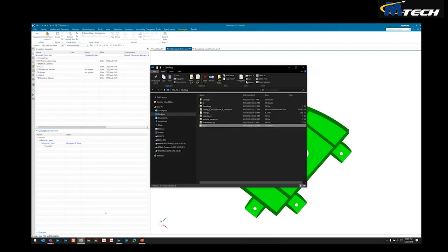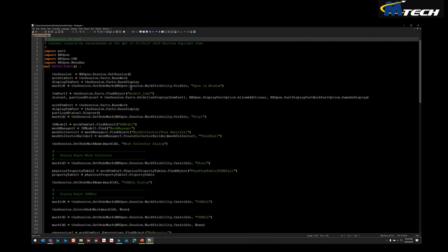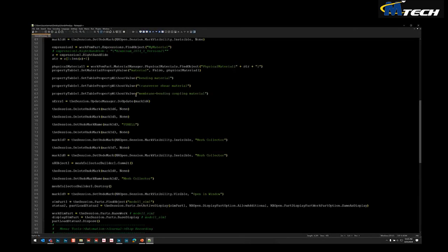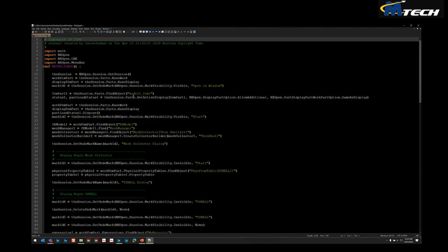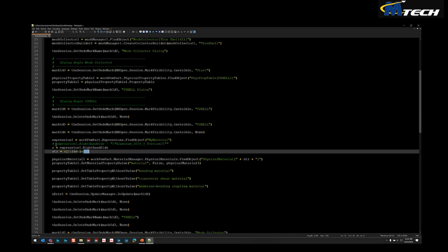So for this example, this is the part where the low code portion comes in. I recorded a file ahead of time, and everything in this file was generated by Simcenter 3D's recorder. Think the same thing you've heard about recording macros in Excel. And we only need to make a change to 5 lines in order to now automate the material modification process through HEEDS. And here are these.